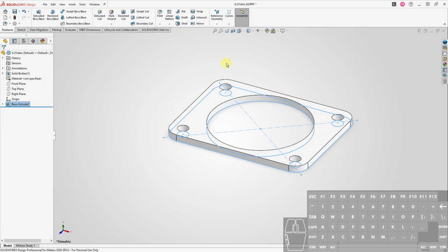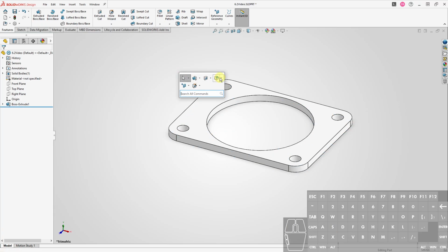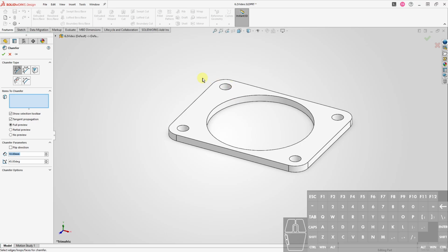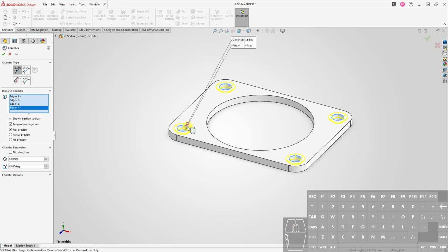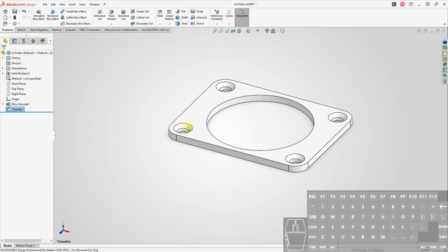Now before we forget, we're going to add the chamfers too. Let me practice using the S key, and then click, and then chamfer to, and it's going to be, let's see, 1.5 to here, here, here. And by the way, when you're clicking, be careful you don't accidentally click on the whole cylinder, otherwise it's going to add a chamfer to the top and the bottom, and it might be hidden, so it might be hard to see. So just be a little bit careful here. And here, I'll hit enter. There we go. Chamfer's taken care of.